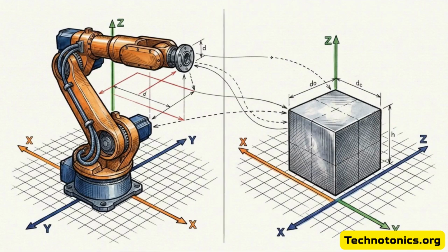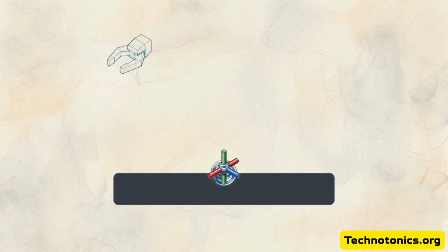This diagram shows how we define and adjust the reference frames. We take the mismatched X, Y, and Z axes and slide them into perfect spatial alignment directly over the workpiece. Once the grid is set, we define the tool center point, or TCP. This dot acts as the absolute focal point for every interaction the robot makes with the target.